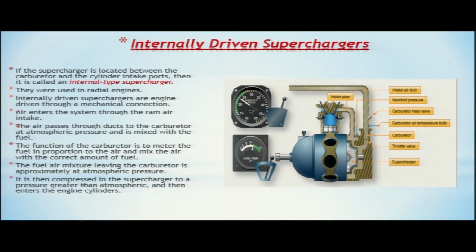These internally driven superchargers were used in old radial engines. So they are not being used now, but they were used in earlier radial engines. Internally driven superchargers are engine driven through a mechanical connection.